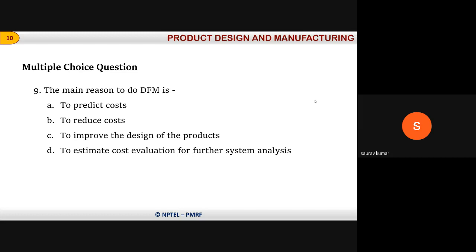One thing is that with DFM, I am familiar mainly with plastic products. The main thing is that I release the 3D of the part along with the drawing. The mold maker sends us the DFM PPT stating how many cavities are required, how much tonnage of the machine the part would run on, the core, cavity and parting line, and issues related to the design, which he is going to highlight.